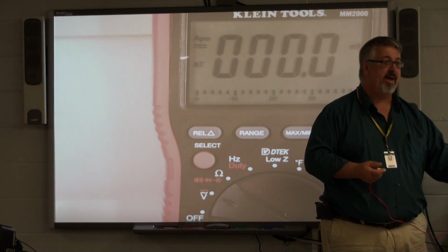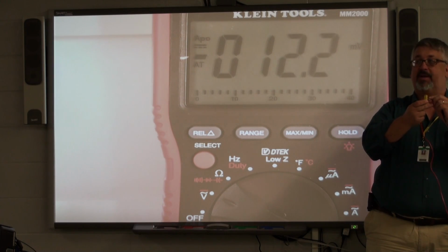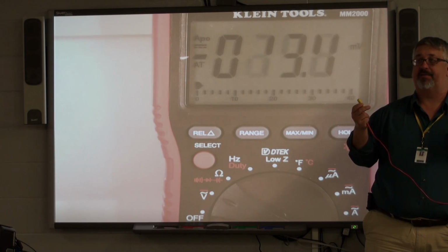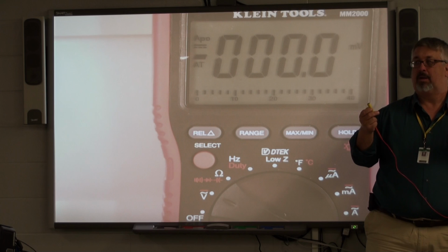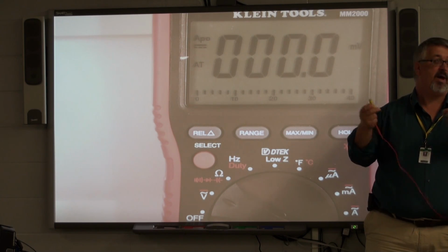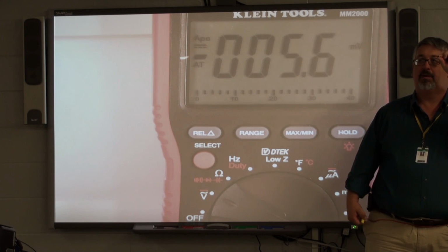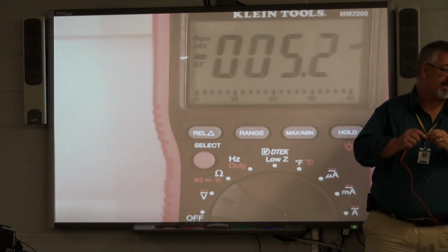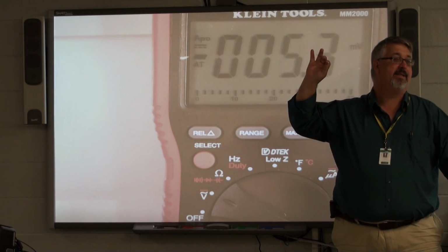Some of you may be asking, how can this itty bitty thing supply 3.2 volts, and this much bigger battery supply 1.5 volts? What's the difference between these two batteries besides voltage? Material. But what ultimately? The use. What does use come down to? Am I going to have a flashlight that has this type of battery in it? No. It's going to be some low current application. And that's the key. Typically you'll see this in a PC as a battery that retains BIOS settings, and it uses very, very low current.